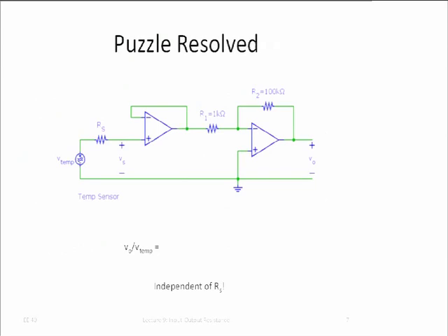What is the gain of this stage here? 0. Oh, no, better not 0, huh? Yeah. Okay, the gain of this is just 1. Actually, we can see that very easily. How can we see that? Well, it's negative feedback. We see that right away. The voltages at the two input terminals of the operational amplifier are the same. One of the two input terminals is connected to the input, the other one is connected to the output, so the input and the output must be the same. That's what this circuit does.